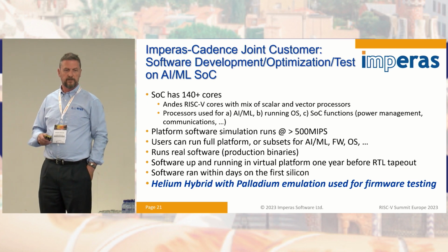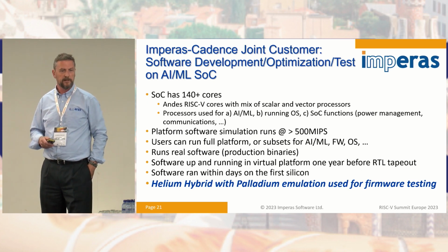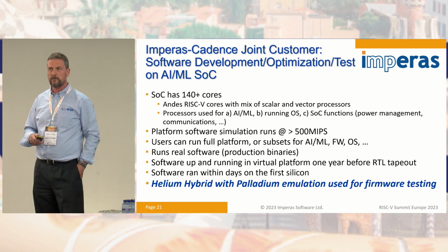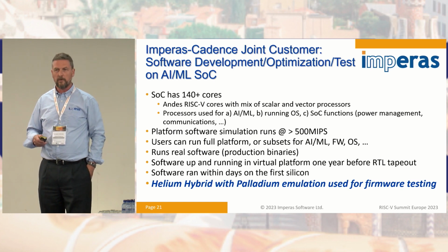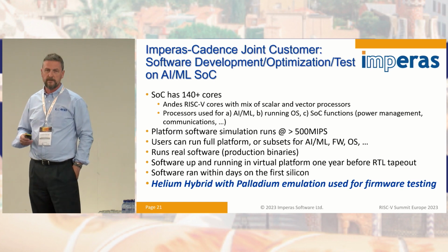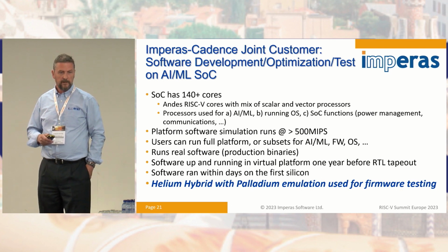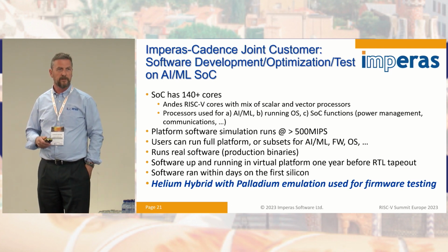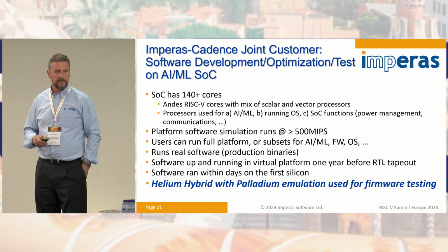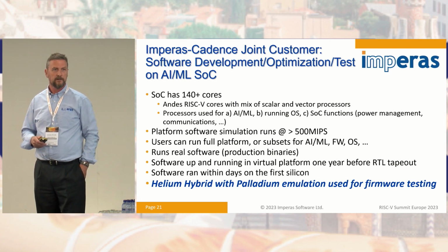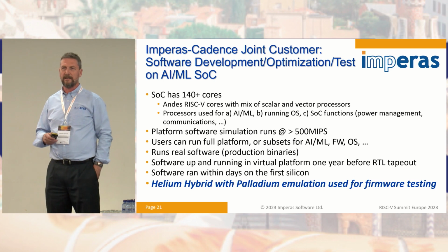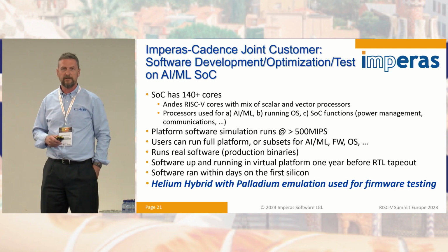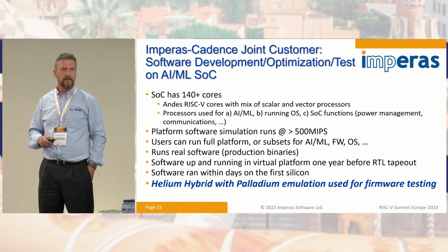The total platform simulation runs at over 500 million instructions per second in simulation, and the users can choose whether they're going to run the whole firmware stacks, they're going to run particular drivers, or essentially run the bit that's of interest to them. They actually got the software up and running a year before the RTL tape-out. Once they got the RTL back, they had it running within days on that SoC. So this is a key thing here. We want to make sure we've got in a position where we get everything in place, so when we have got our SoC back, we're already pretty much up and running and fully tested.